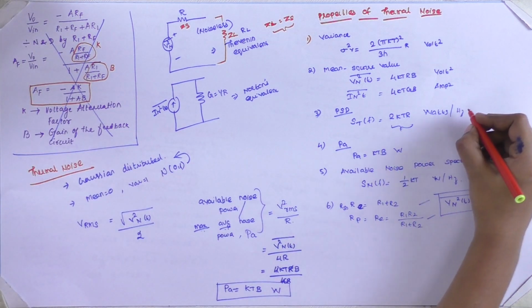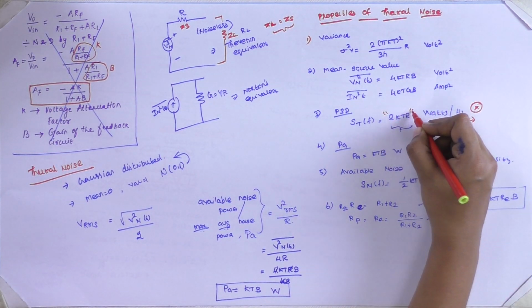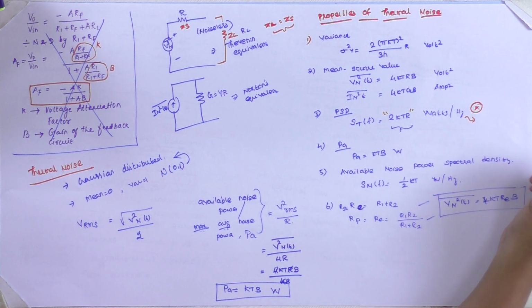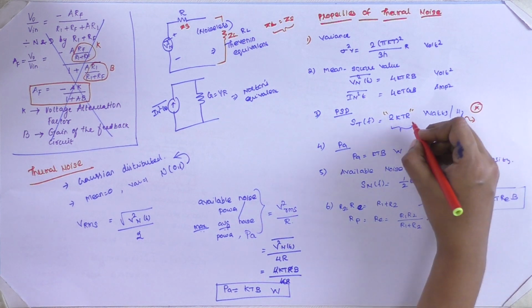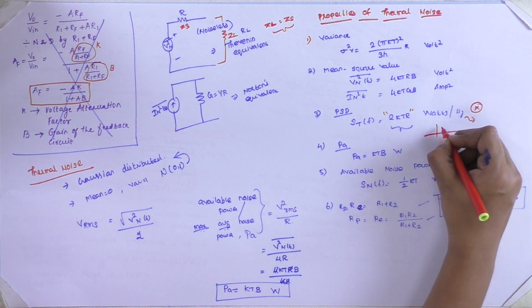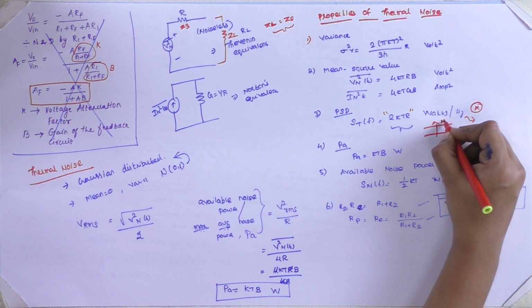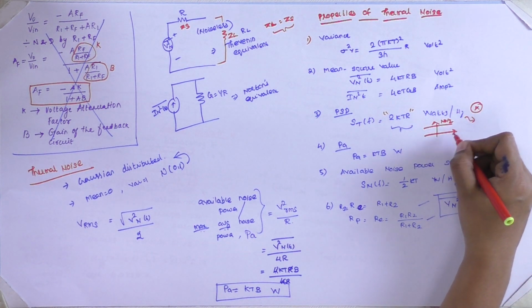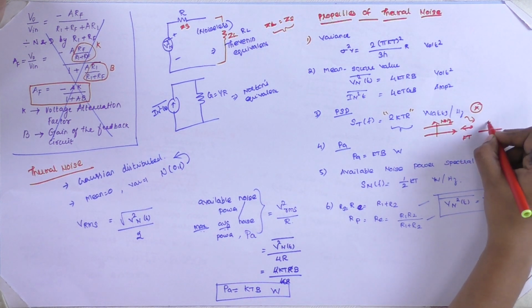From this observation we identified that due to the power spectral density's constant nature, the autocorrelation function will also be constant. Just now we observed the white noise process, which is N0 by 2; if this is constant in nature, the Fourier transform of it will give an impulse function.